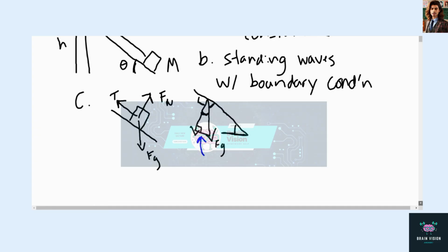180 minus 90 for the right angle gives 90 between the angle that I just drew and the angle we're interested in. And since we know that the angle that I just drew is 90 minus theta, if we have 90 minus 90, the point is, by doing a little bit of analysis, we'll find that this angle here is equal to theta, which helps us figure out what relationship between theta and FG gives us the parallel component.